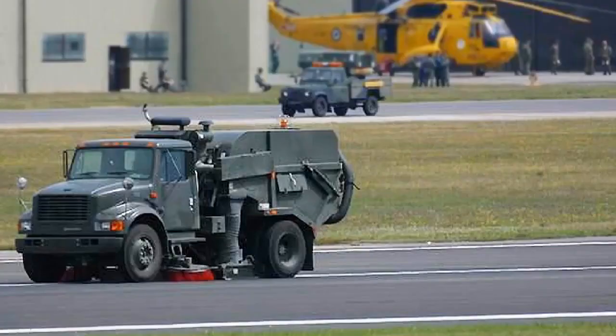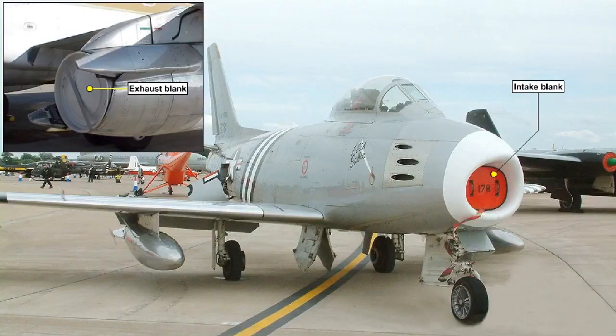To prevent damage occurring from foreign object ingestion, it's essential that the operators of gas turbine engines should take precautions which preclude the entry of debris into the ramp area. After flight, intake and exhaust covers should be fitted to prevent ingress of contaminants and also help to prevent the engine windmilling.